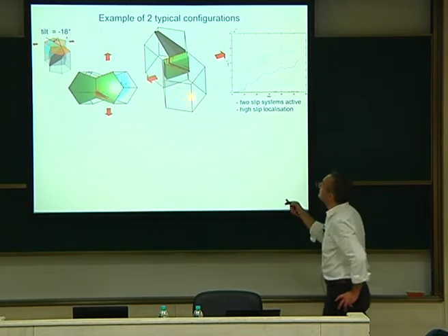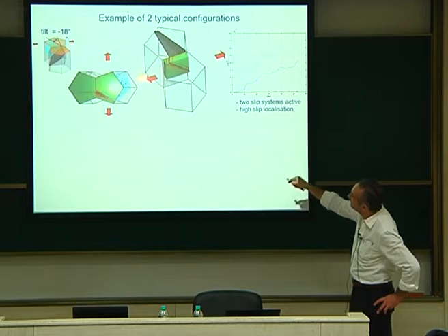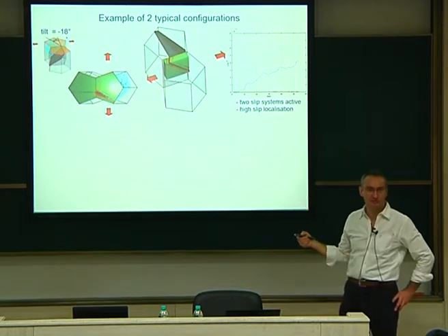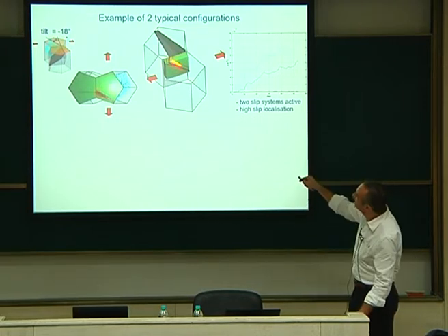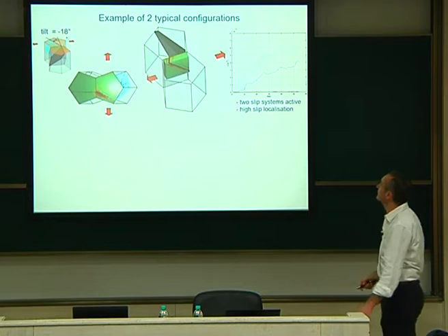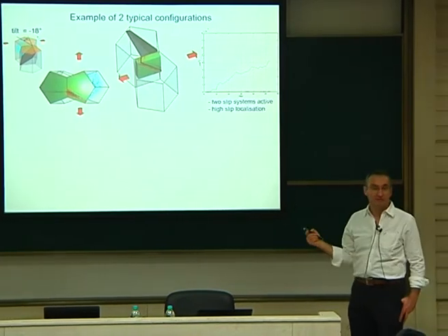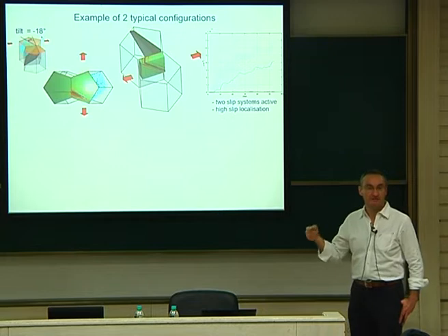Okay. And if you zoom on this thing, you can see that it is indeed made of slip bands like that. This is the crack slip plane. It's hard to see in 3D, right? We should have the 3D view rotate to look at it, but you see the slip plane like that, and you can see that it is not very thick. Everything is concentrated. So here is something which is very bad for the material. It will highly localize. In other words, this is a very fast crack transfer.